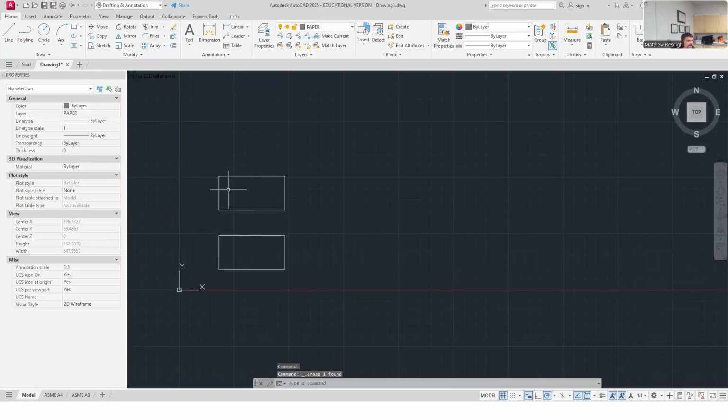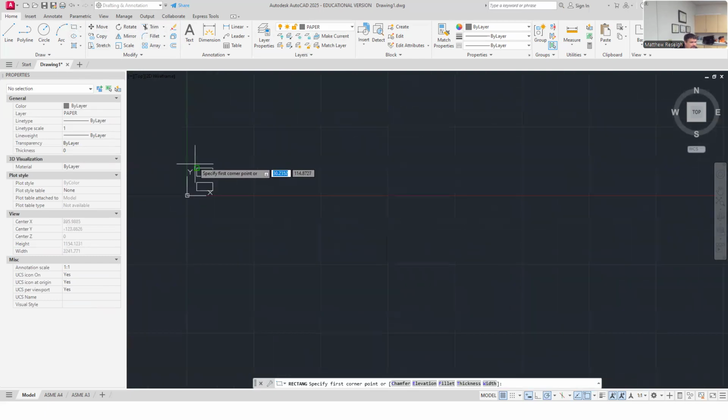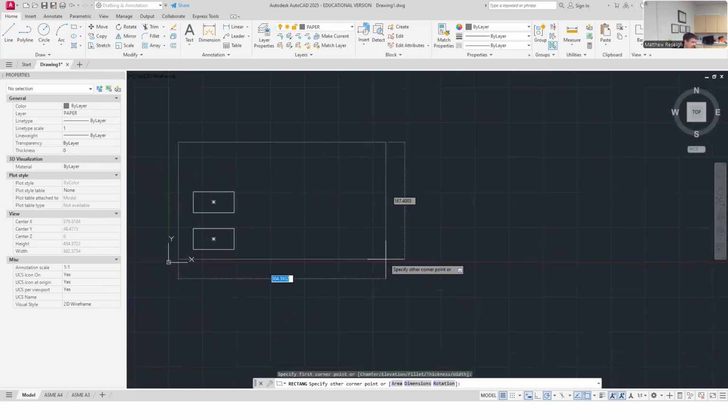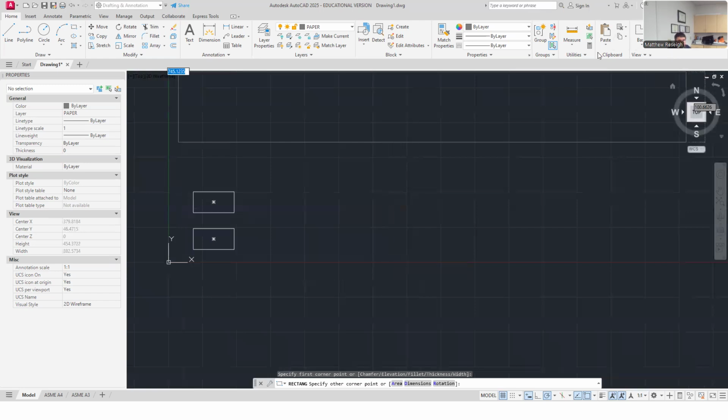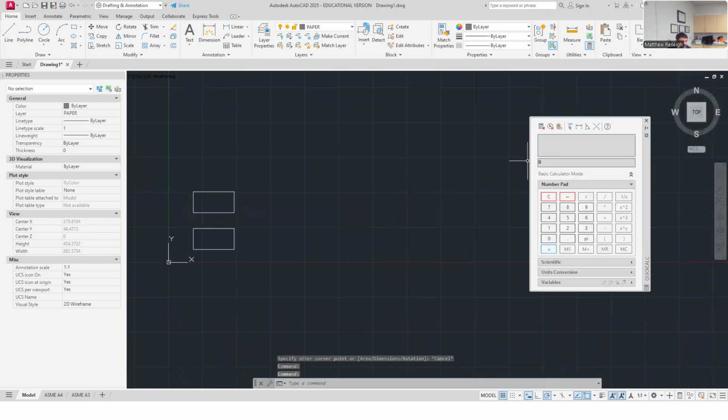What we're saying is these are gonna end up being half scale. So I actually have twice as much room. If you notice, it looked like I would never be able to fit that on that rectangle, because technically this is going to be twice as big. So I could draw this at what's 272 and 172 twice. 272 times 2. That's how many millimeters I have, 272 widthwise. But I can be twice as big as that because I'm going to be at half scale.